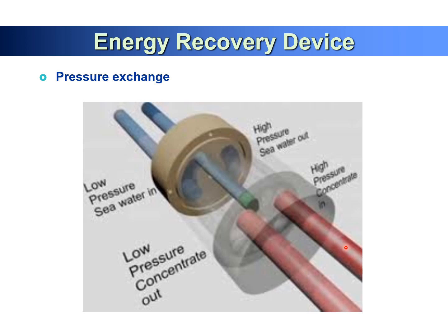And one small problem is that whenever they push it through, they touch a little bit of seawater at the surface here, so the concentration is slightly high, but compared to the energy saving cost, this is very marginal. So that's one way of the pressure exchange, currently applied in 3 desalination plants in Australia. Also we have different.